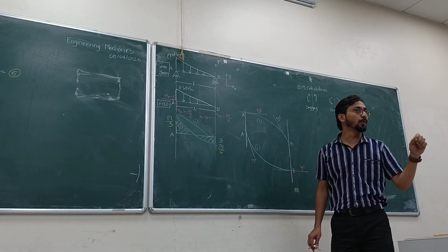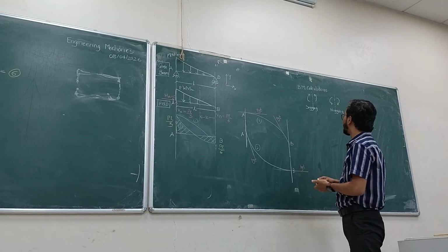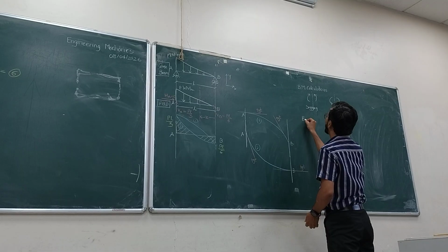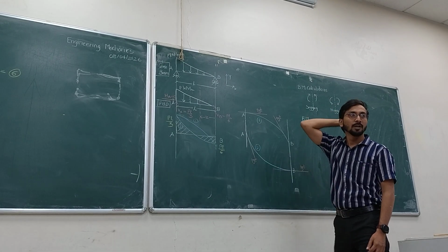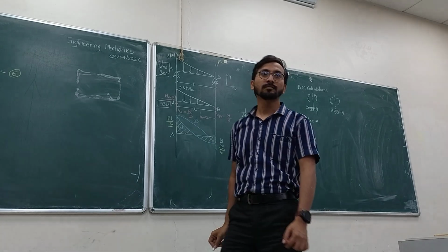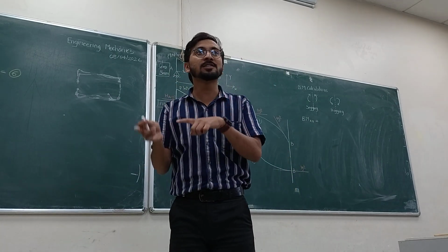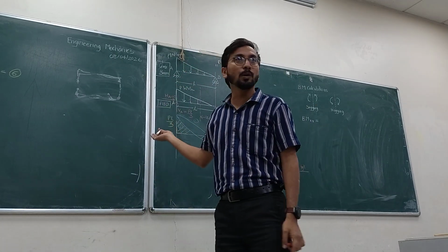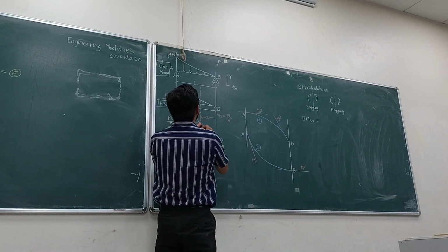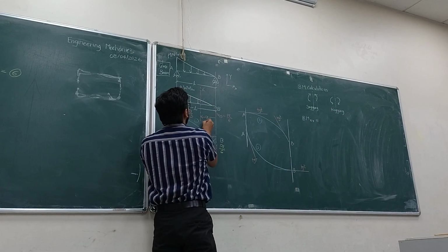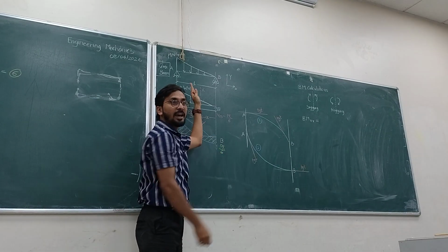So can we write the equation of bending moment at XX directly? Let us write this. So bending moment at section XX is equal to. What is the bending moment again? Sum of moments on either on left or right. Where we are looking at this point? Right side. So let us look at the right side of the section. This is your x-axis.